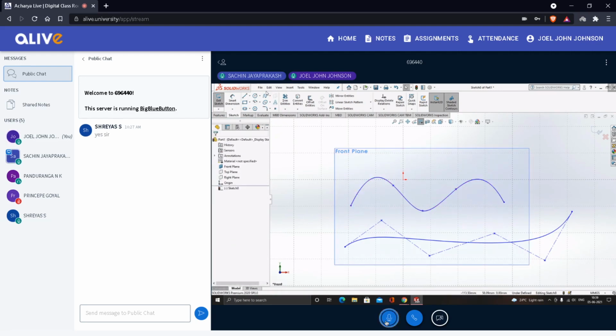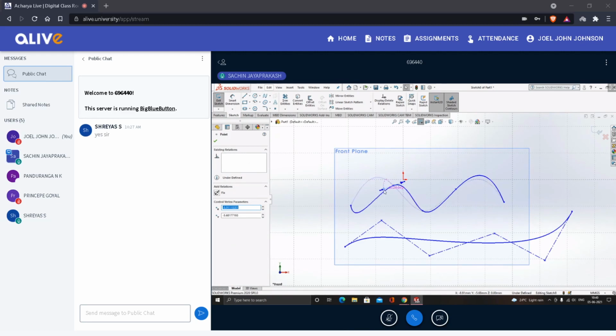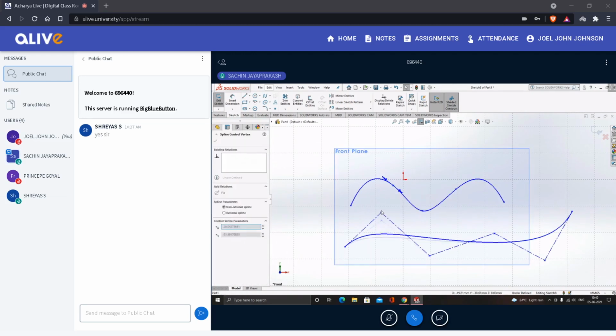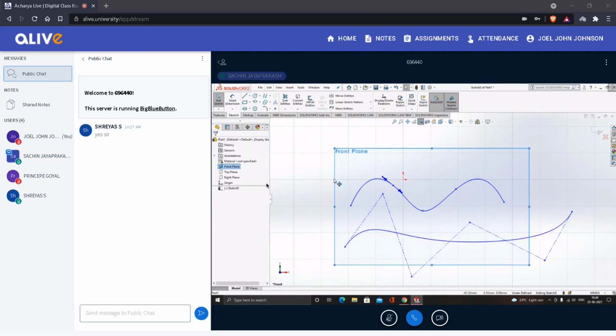If you draw the first type of spline, you get EPs. You can also control your line with EPs, but it is not as flexible as CVs. There is some sort of limitation. But in CVs you can control end to end of the entire curve, and you can add a number of CVs more based on how complicated the curve is. So this is all about splines.